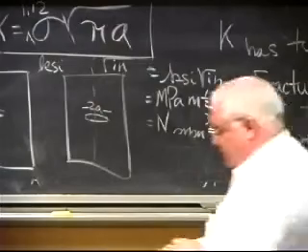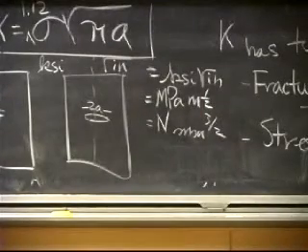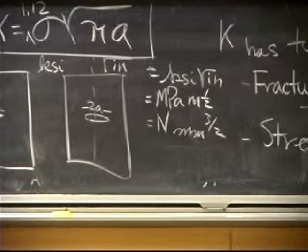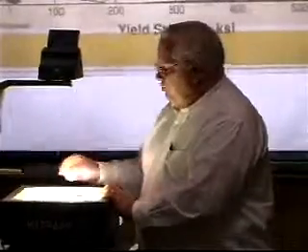If I go back to these ratio analysis diagrams, you'll see as the yield strength goes up higher and higher, the fracture toughness in KSI square root of inch goes down, and I start running into problems. In fact, I get below 100 at 300.